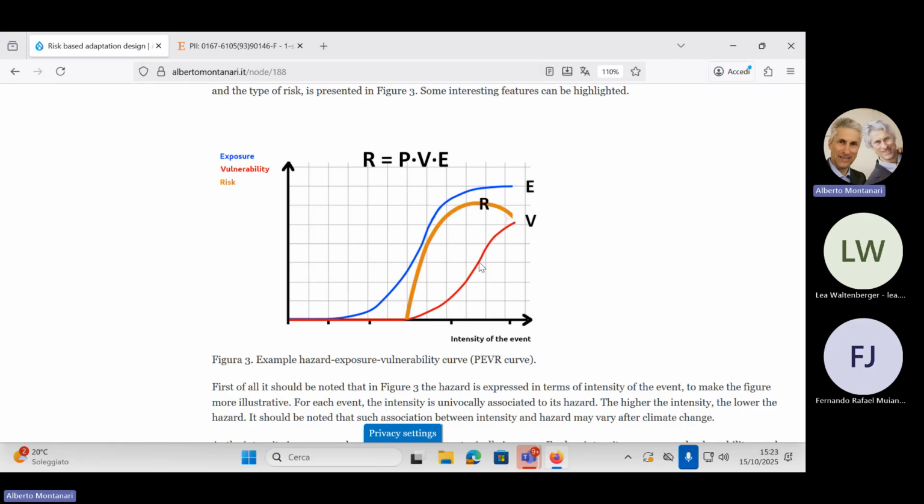The most relevant things from an environmental point of view are wind speed and earthquake. And wind speed is probably more concerning than the earthquake because it's more subtle. It's also related to the possibility to cross the bridge with trains, which have very little tolerance with respect to oscillations. Cars are more tolerant. Okay.